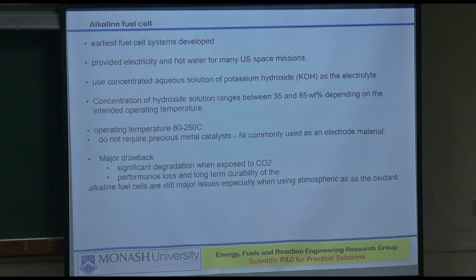The electrolyte is alkaline hydroxides, and the concentration of the hydroxide solution, that means the electrolyte solution, is anywhere between 35 to 85 weight percent, the rest being water. Operating temperatures are 80 to 250 degrees Celsius, they do not require precious metal catalysts, and nickel is commonly used as an electrode material. But the major